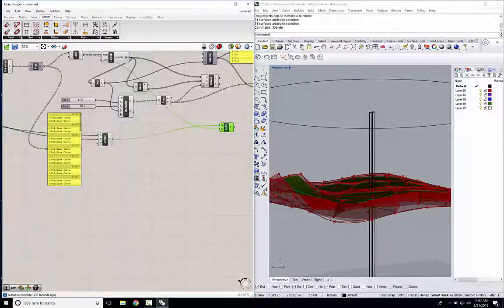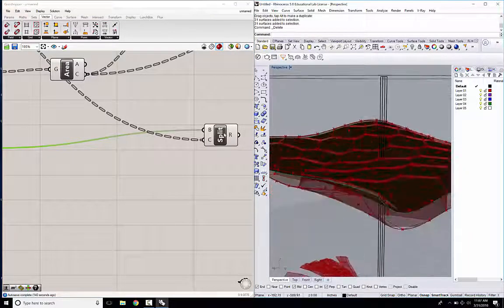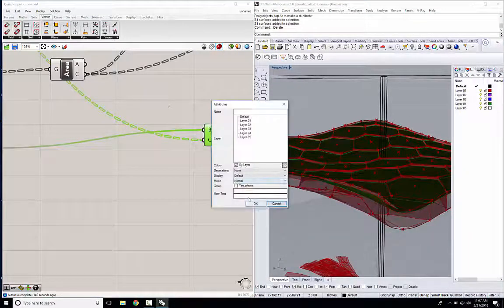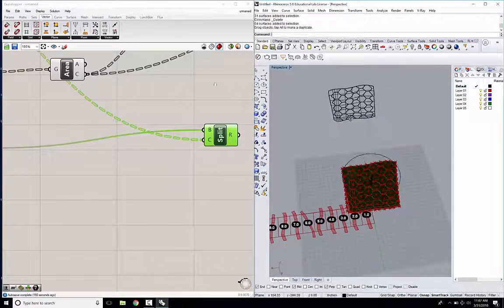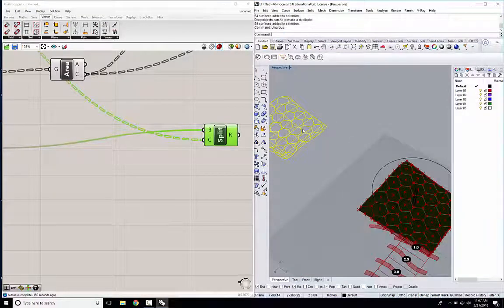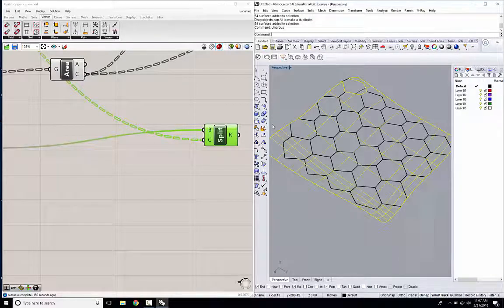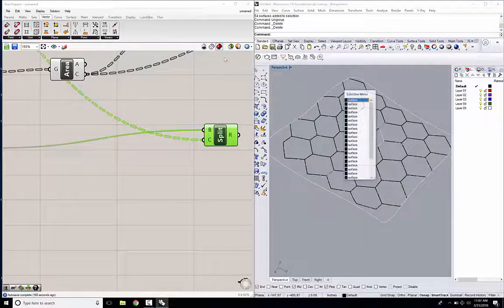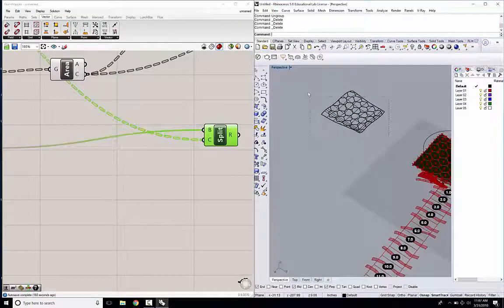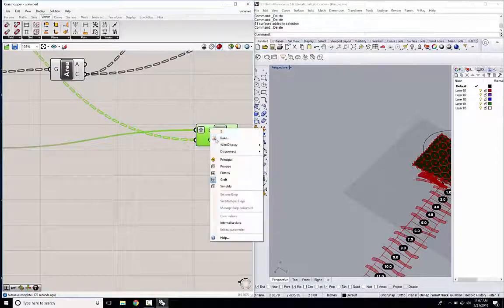And let's try, so this looks like it is also having a grafting problem. But let's just try baking it to see what we're getting. So I'll group it, select it, move it out, ungroup to see what we're getting. Yeah, so each individual surface is creating an outside one. So you can tell this is a grafting problem where each object is being recreated. So I'm going to graft that surface and see if we can reduce.